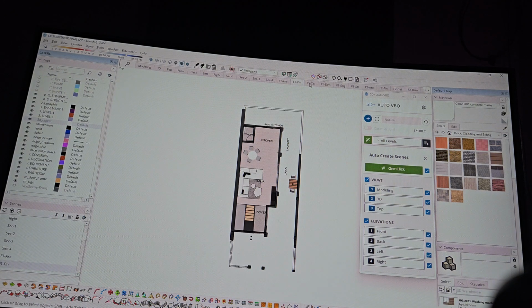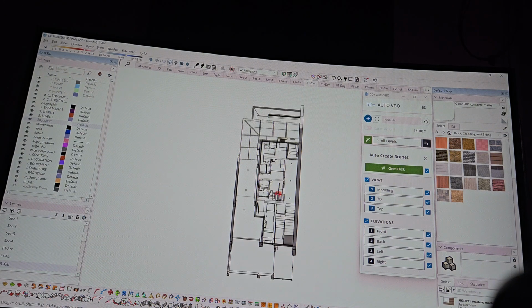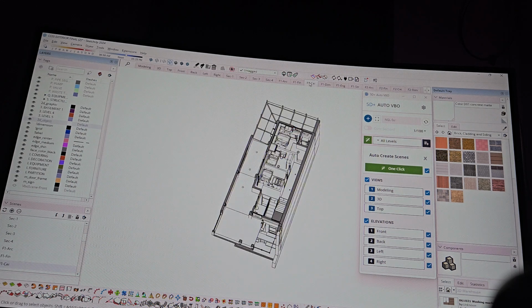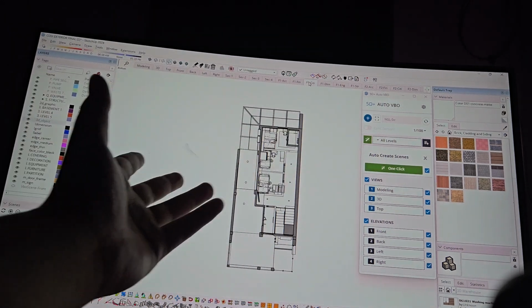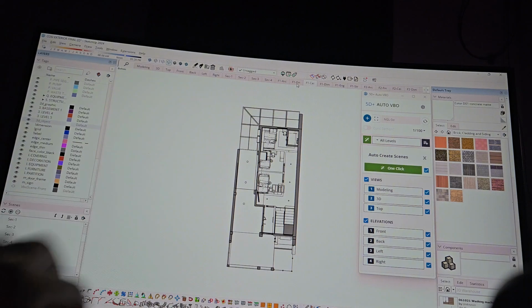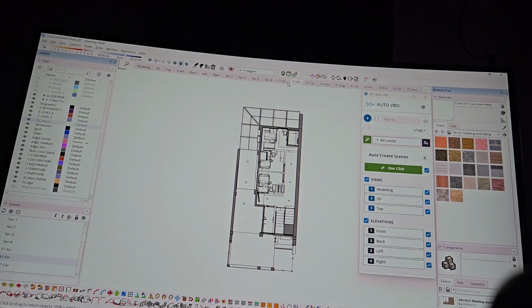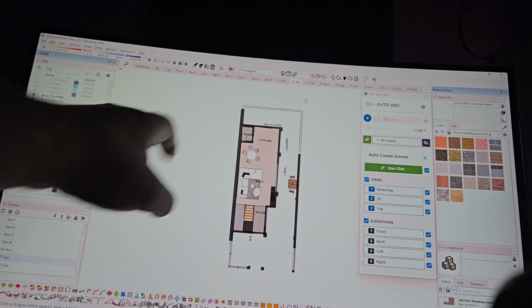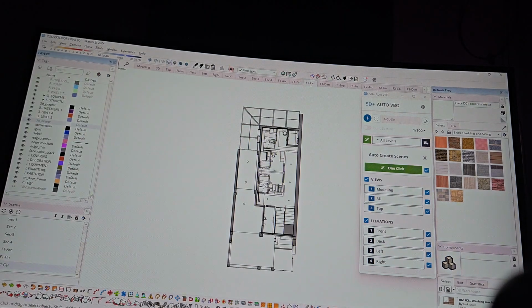Okay, next we have ceiling. So what ceiling actually did was look from below. The problem with this is it's flipped or mirrored. Oh no. So if you actually check this one out, this is the bathroom, powder room. It went here. So what you could actually do here is go over to layout and then flip this thing. Okay, that's what you can do, but actually I don't do that.